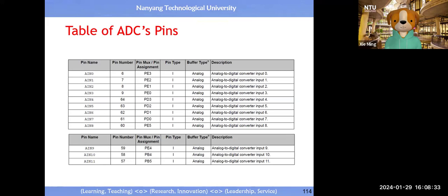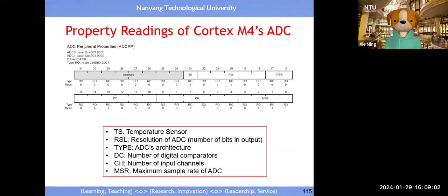And here, if let's say you have 12 sensors, how do you physically connect the sensors to the microcontroller? Then you use this table to know the connection. In the first column you see analog in, AIN0. AIN is analog input 0, right? Analog input 0 all the way to analog input 11 means what? 12 sensor inputs, right? Clear?